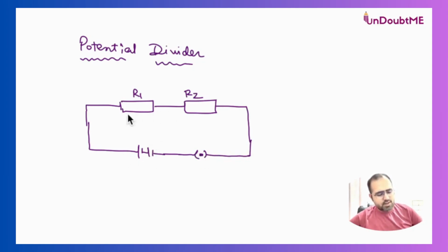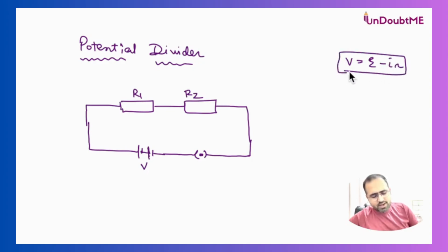Now, since it is a series combination and the net voltage supplied by the battery, in such cases, we always consider internal resistance to be 0. Even if the internal resistance is something, just try to recall we had discussed V is equal to E minus Ir, where V is the net voltage supplied by the battery. So we can just say that V is the net voltage, and in the direction of the positive terminal we will take current. Now when current goes through both the resistors, they will have different potential values because V is equal to IR is the formula which we will be using.